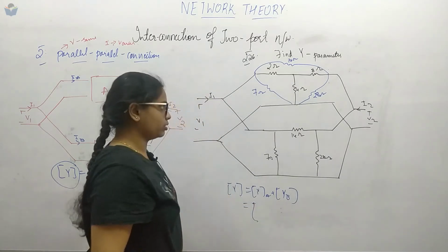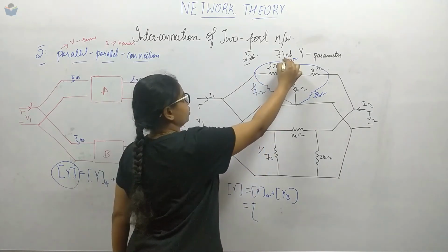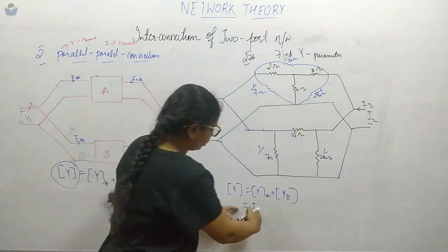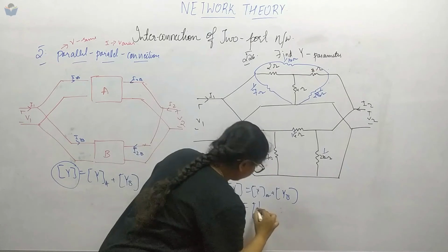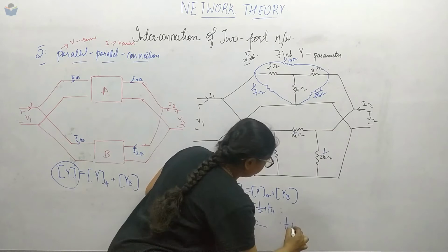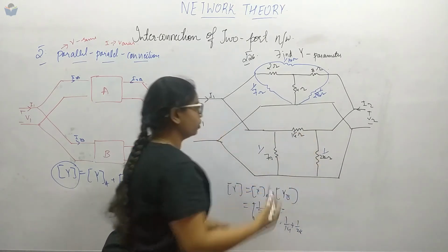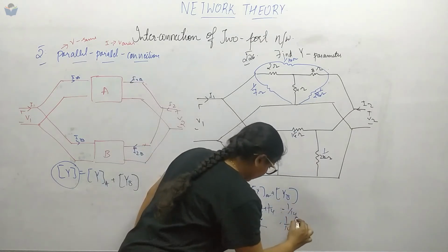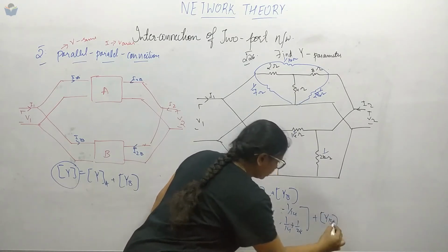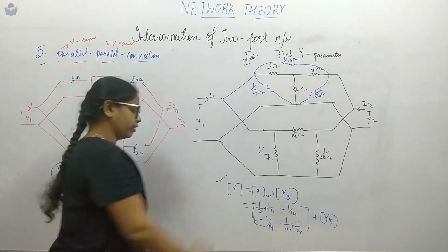Now here the twist is, for calculating the admittance, you have to take 1 over everything, whatever value you have got. So to calculate Y11, it is the same thing, 1 by 7 plus 1 by 14. Similarly for Y22, 1 by 14 plus 1 by 28, and this will be the negative of this whole thing, that is 1 by 14 minus 1 by 14. Same thing, YB is equal to YA. So write this matrix over here, then add it, you will get the Y matrix.